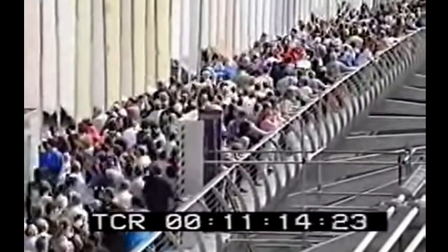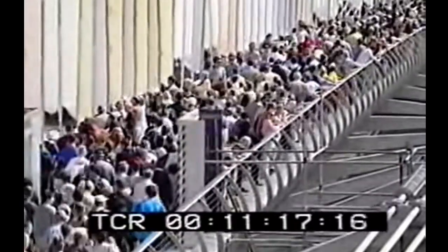You can see on the inauguration day, a lot of people walked through the bridge, and now you can see the swaying of the bridge, which was obviously causing discomfort to the pedestrians on the bridge. There is quite a visible shaking and swaying of the bridge. Structurally, the bridge might have been okay, there was no issue structurally, but the excessive vibration in the bridge definitely didn't meet the serviceability requirement of the design.